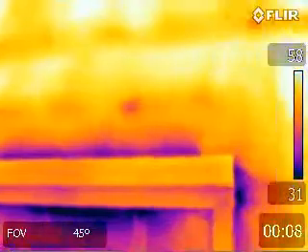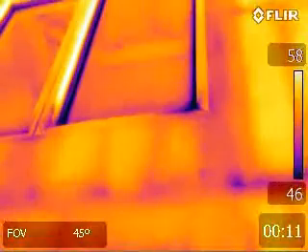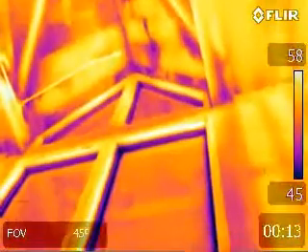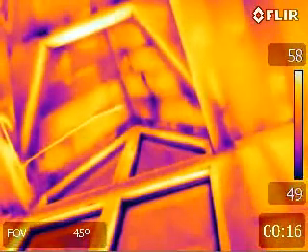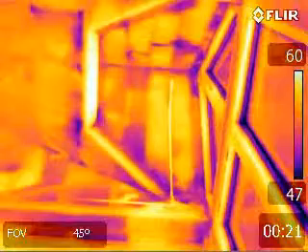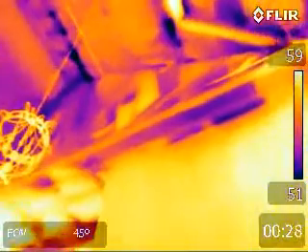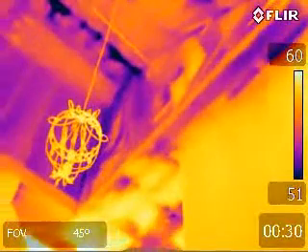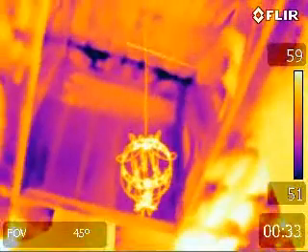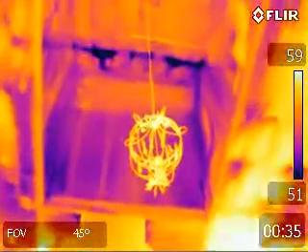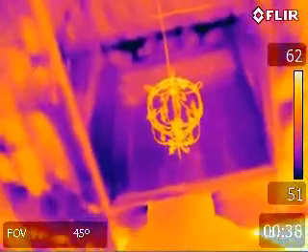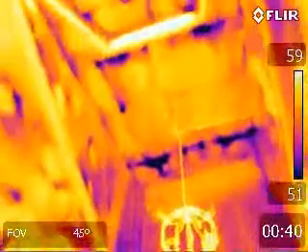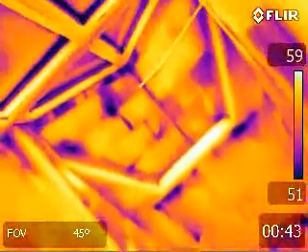We're looking at a Shotz Thermal Imaging video for the purpose of looking for air infiltration, missing or poorly installed insulation. The darker colors represent coldness. The brighter orange yellowish colors represent warmer temperatures. As we can see, this big over roof structure, there's a lot of missing insulation and poorly installed insulation.